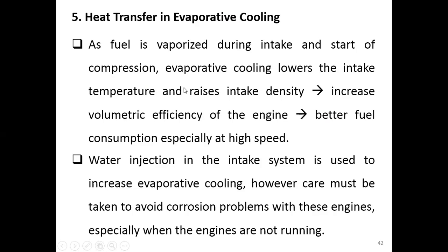This evaporative cooling lowers the intake temperature and increases the intake density. That means it increases the volumetric efficiency of the engine. And since the volumetric efficiency of the engine increases, we have better fuel consumption, especially at high speed.